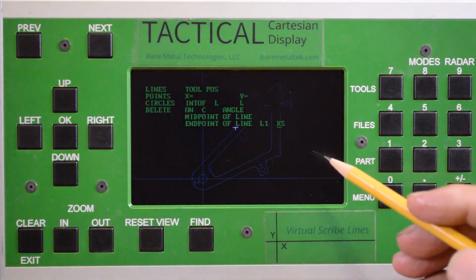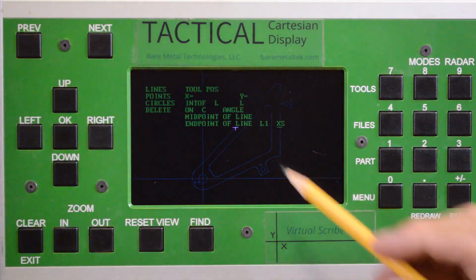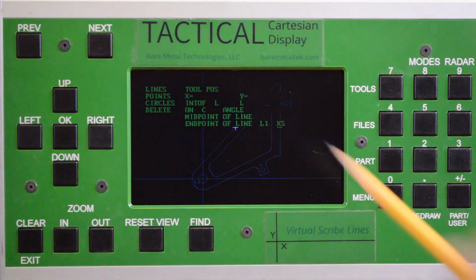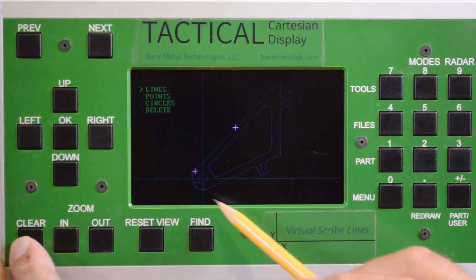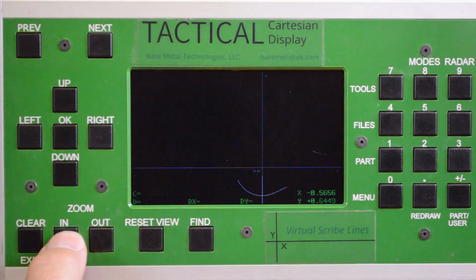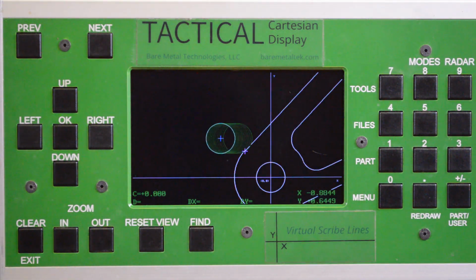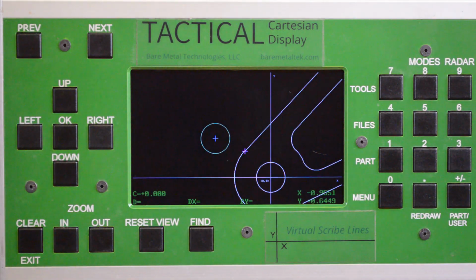You'll get the hang of how these modifiers work. X small, x large, y small. So we're going to pick the x small point, right? Remember, there's always two solutions whenever it's giving you this choice. Okay, so let's pick x small. And there it is. Point 34 is, let's zoom in on it. There it is. Right there, that's point 34. Get the cutter out of there. See? Okay, so that's that.